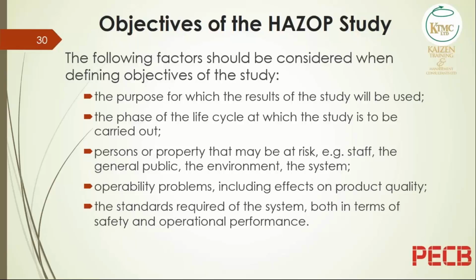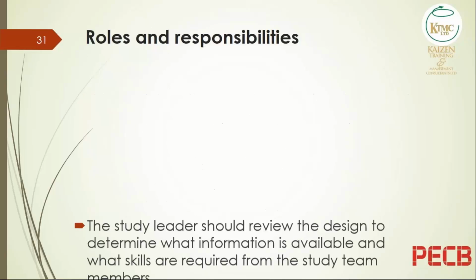Operability problems, including effects on product quality. So remember, in HAZOP we look not just at hazards related to health and safety, we also look at operability. Are there issues related to maintenance, operation of the system? The HAZOP brings this out. The standard guide of the system, both in terms of safety and operational performance. So HAZOP does that for you.